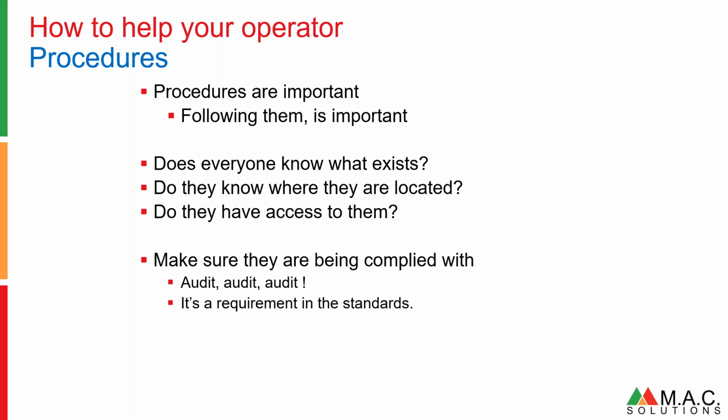It's great to have 10, 20, 50, 100 different procedures that cover absolutely everything. We've got everything in place, a procedure for absolutely everything. But if nobody knows where they are, nobody follows them, complies with them, they're absolutely pointless. So you need to make sure that you audit that what the procedure says is what the operator does. Audit the procedures to make sure they're correct. Is the procedure still valid? We've upgraded, we've changed our control system. We can't do that. That's why we don't follow the procedure. The procedure is wrong. Make sure the procedure is correct.